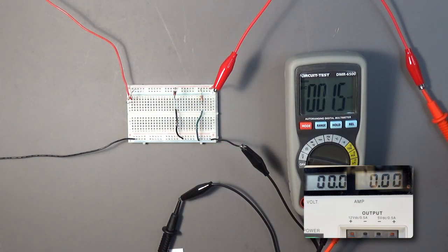So as I turn the voltage up on my power supply, you'll see that voltage goes up here as well. So at 1 volt, we're at 0.9 volts here. There's a current limiting resistor in there, and that's why that's a little bit different. But as I go up, now to 1.5 volts, 2 volts, 2.8 volts, 4 volts. We're now at 5 volts, and this is kind of peaking out around 2.2 volts or so. Now it's 7 volts. And so it's keeping our voltage down around 2.5 volts.